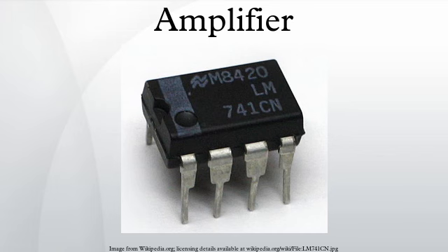Calculating the values of the circuit's resistors and capacitors is done based on the components employed and the intended use of the amp. For the basics of radio frequency amplifiers using valves, see valved RF amplifiers. Notes on implementation: real-world amplifiers are imperfect. One consequence is that the power supply itself may influence the output, and must itself be considered when designing the amplifier. A power amplifier is effectively an input signal-controlled power regulator, regulating the power sourced from the power supply or mains to the amplifier's load.